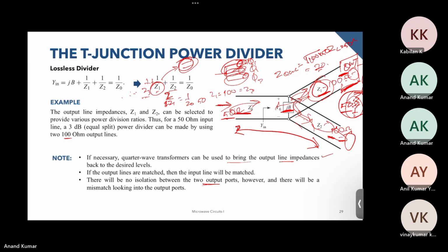So I get your question. I think you're asking, for example, we have this 50 ohm over here, and then we divided this into 3 arms. This was 50, and this became 100 ohm. All of this is 100 ohm, and then we wanted to get 50 over here. So these are 50 ohm lines, and in between we use some quarter wave transformers, and we want all of them to be of the same phase.